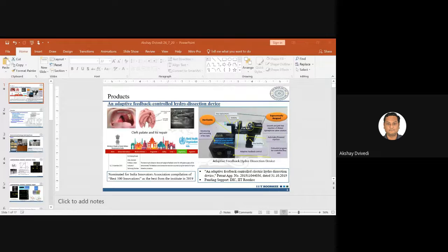So if I consider this particular zone, and if I compare this zone with what I get with respect to electrochemical discharge machining, you can find that there are certain peaks of voltages that you can identify, which are quite less as compared to what ECDM with a conventional tool or a smooth tool is doing.